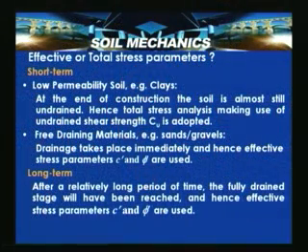Now, this stability analysis is required to be carried out for short term and long term conditions. Short term stability is carried out for low permeability soils where drainage is not permitted, and long term conditions are where drainage can occur and the fully drained stage can be reached. In that case, C dash and phi dash parameters are required to be used.